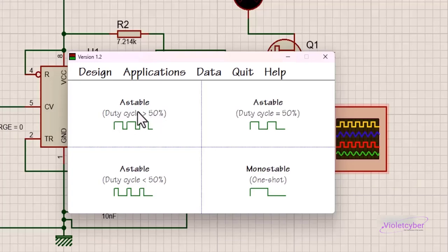If we want to produce a duty cycle equal to 50%, it actually gives 50% of the pulse. Now you have learned this discussion of 50%. Then we will consider a period of time, for example, a second, well, and half of this 1 second, which is half a second, is 50%. That is, if, for example, we want to rotate a 12-volt motor at half its speed and power, we can use this section, and this circuit will give us a pulse of 50%.